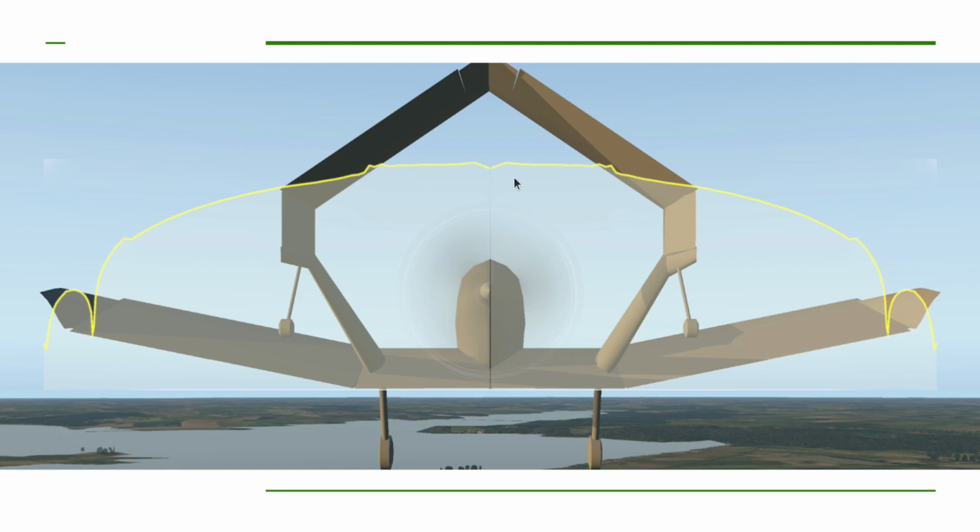So you can see it's pretty level here in the middle and pretty high, and then as you come out to the tip, it starts dropping off. And then it's got this little funny dip here where you have a significant dihedral change on the tip. In fact, just about anywhere you see a dihedral change, you can see a change in that distribution.